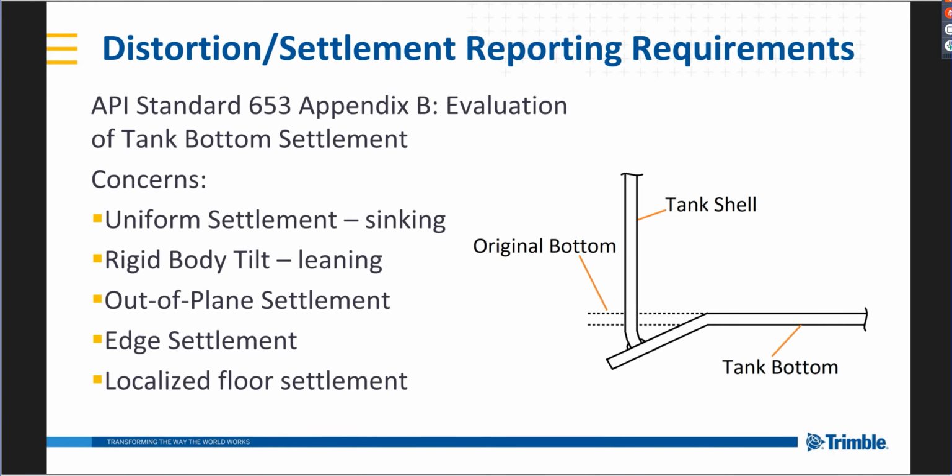Now, another thing that's of particular interest to inspection and construction is the settlement, the edge, and being able to look at this and know what's going on over time, because you've got all of this weight pushing down on the outside of the bottom of the tank. These shells are quite heavy, and they'll certainly start to bend down slowly over time, or have the potential to.